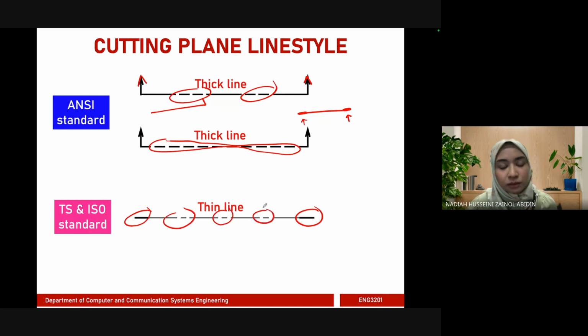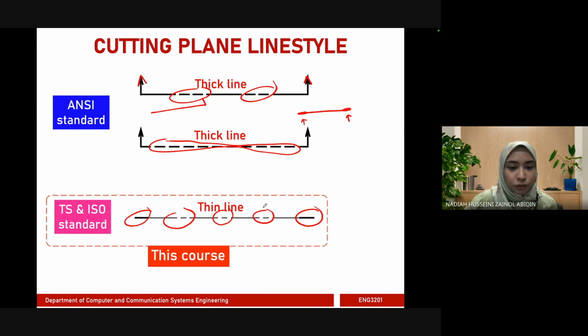So please take note, when we are drawing, we will use this. This course will be using this type of section path. Okay, so there are several types. We will be using this one, whereby it's slightly thickened with no arrows. Okay, and the line is almost like a center line.